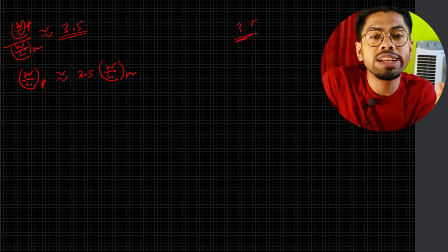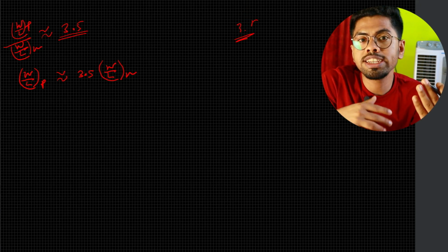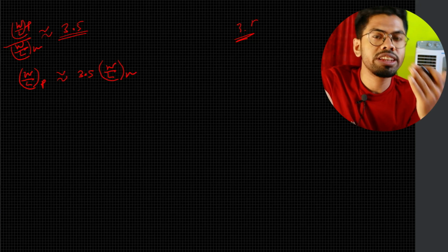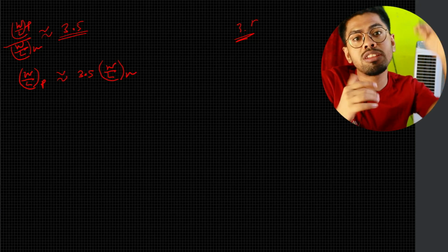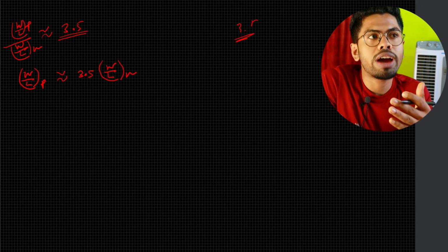There is no golden number of 3.5. It depends on your process parameters and on your voltage. If VDD is 2.5, then you will get some answer. If it is 5, then you will get another answer. So this is a rough sense. Never say that it is 3.5.